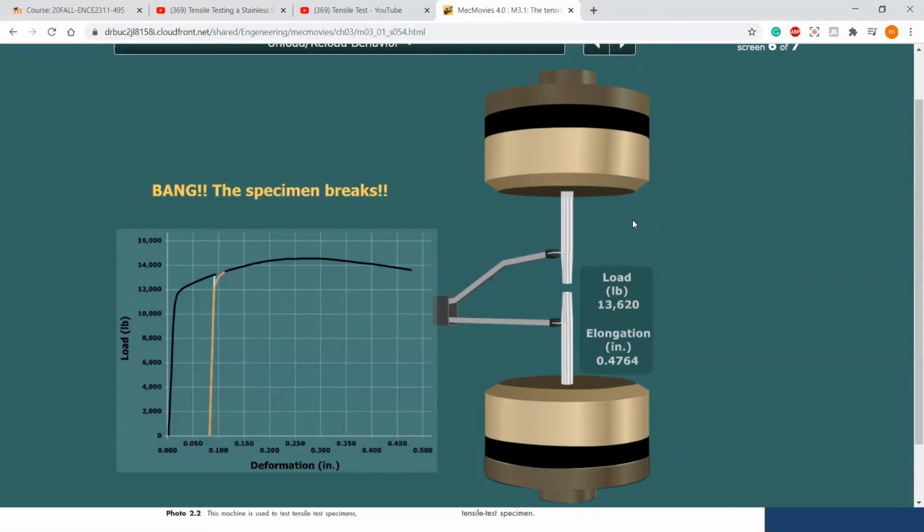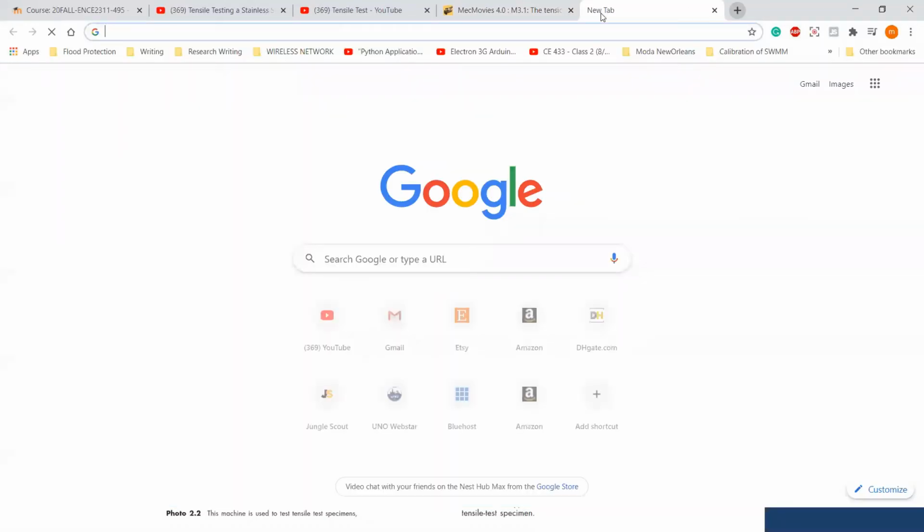Once you finish your design, you submit your final design to the contractor, and they order the steel members in the desired shape. On site, you don't have to bend these steel members, and as a matter of fact, you cannot bend the W shape.